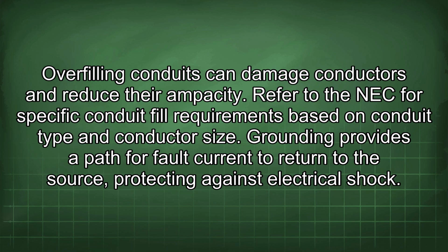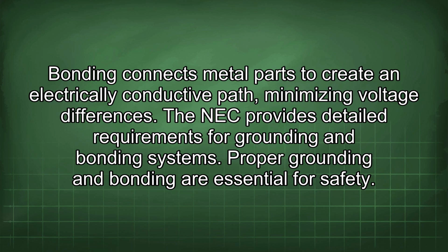Grounding provides a path for fault current to return to the source, protecting against electrical shock. Bonding connects metal parts to create an electrically conductive path, minimizing voltage differences. The NEC provides detailed requirements for grounding and bonding systems. Proper grounding and bonding are essential for safety.